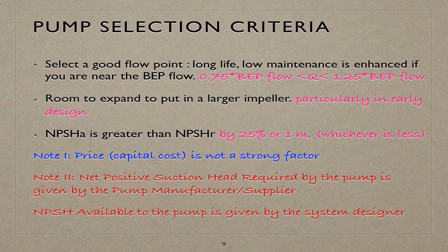Therefore, there must be a certain minimum required suction pressure for each pump based on the flow. NPSHA, which is available from the system designer, must be higher than NPSH required, which is required by the system and is given by the manufacturer.